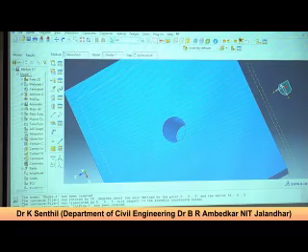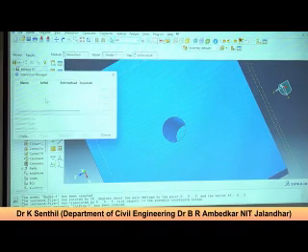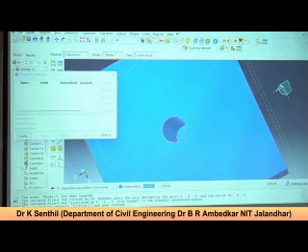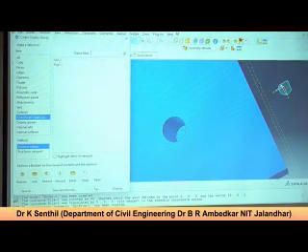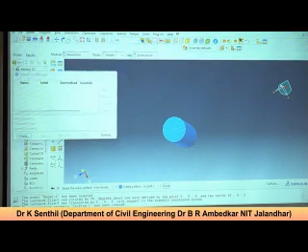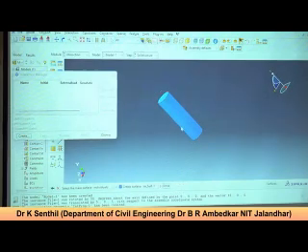Now you go to the interaction manager, create, the same steps that I have done, you just repeat. So now I'll go to tools, display, create, remove soil, add, select the master surface, then surface based one.